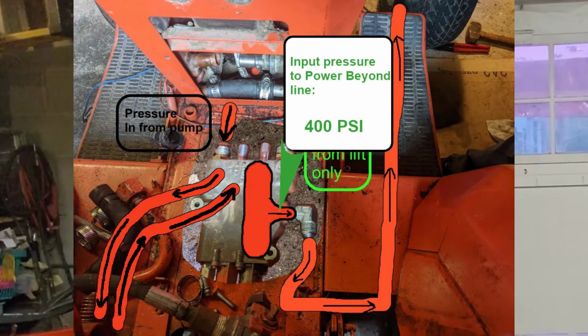If you do overpower it, you're going to blow out the cylinder because it's just not made heavy enough to withstand 2000 psi. So the realization hit me that since the power beyond is downstream of the lift circuit, the power beyond has the same effective pressure that the lift circuit does. That's why the engine didn't strain, and that's why the pressure gauge only went up to 400 psi.